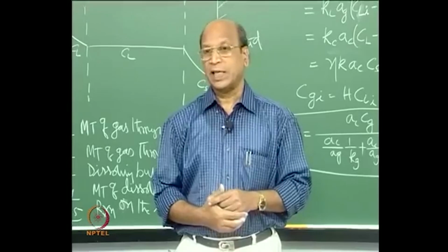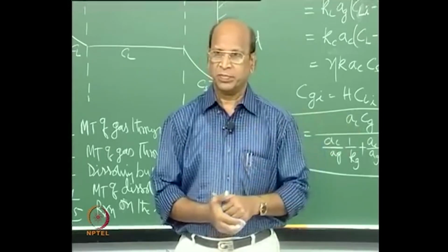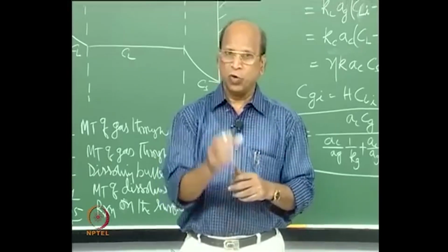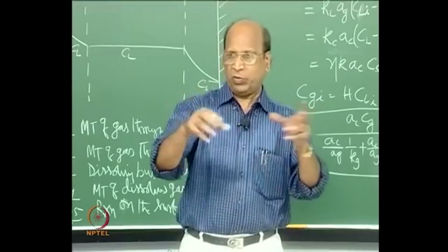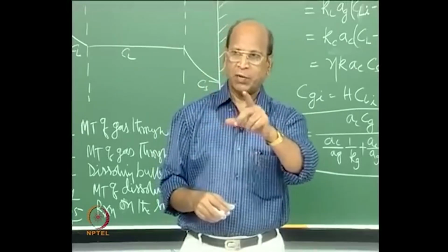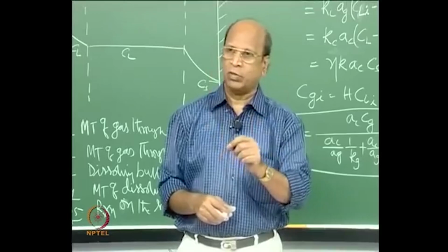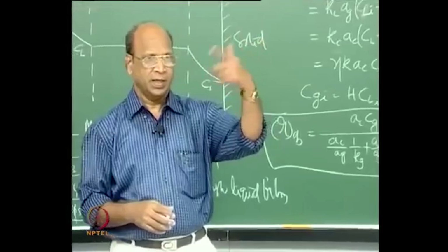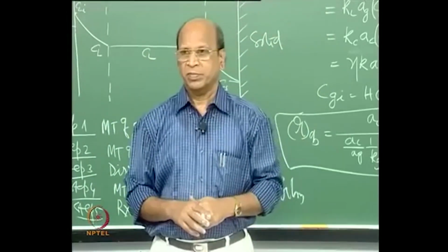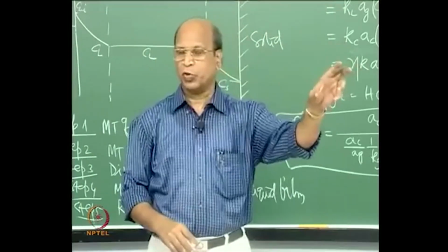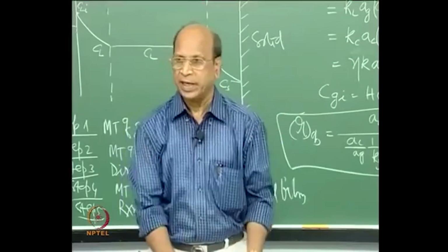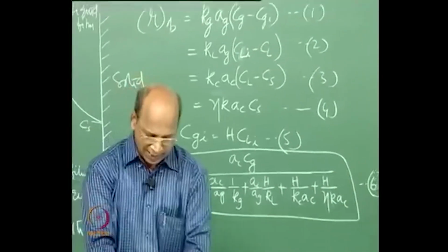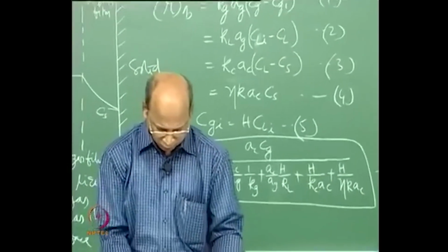In fact, k can be estimated using this technique, that is the pure intraphase intrinsic constant, where you measure all this, then you can separate it before converting that into eta phi square. What you have done is actually eliminated k from that, if you remember the original derivation. So you can go back finally there, substitute and get pure k. That can be done. So now the rest is kL and kC, and kL the mass transfer coefficient.